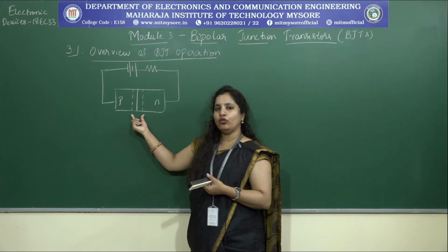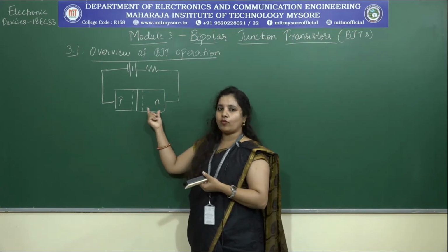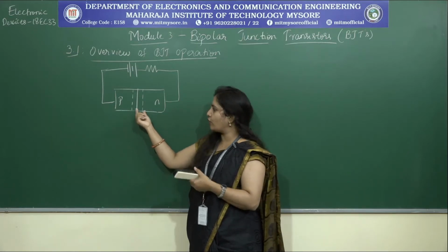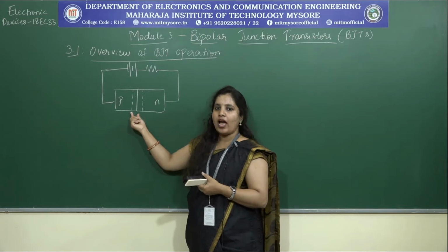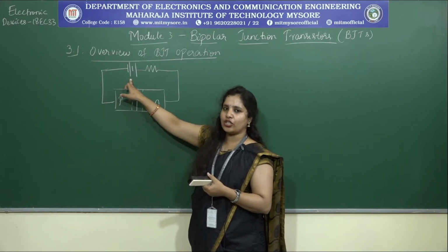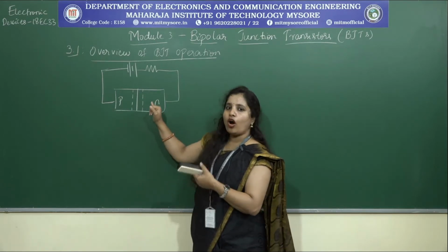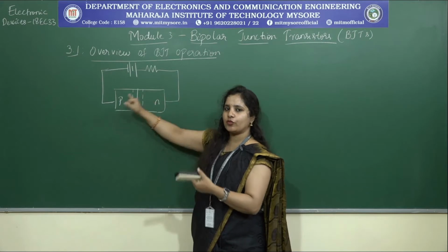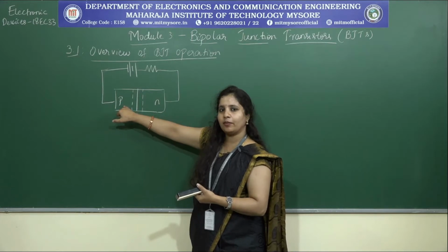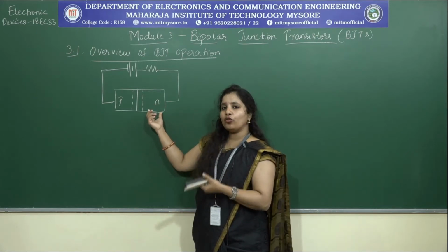While starting off with module 2, you understood this concept in the very first topic of module 2, that is, whatever reverse saturation current is flowing in the device has nothing to do with the intensity of the electric field present in the junction. And this shows clearly that it is independent of the amount of reverse voltage that I am providing. But what is it in turn dependent on? It is dependent on how often the holes present in the n-type get swept to the p-type, and how often the minority carriers, that is the electrons present in the p-type, get swept to the n-type. Right? Now, what does this define? How do you define this factor?